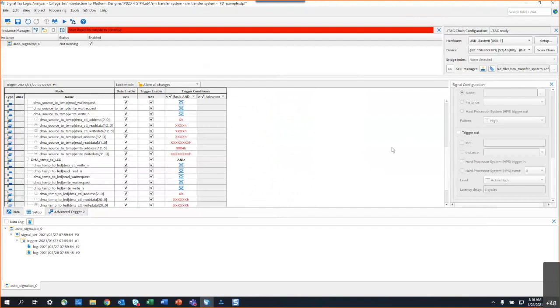Yeah, that's a common solution that our support gives out. Sometimes the on-chip debugging tools don't like 24 megahertz. I've never understood exactly why they don't like 24 megahertz, but they work fine at 6 megahertz.